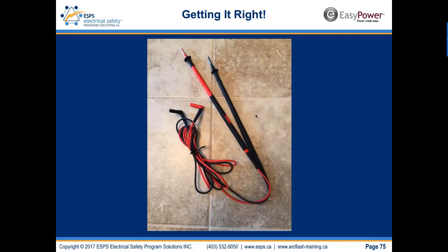There's probe extenders from Fluke that you can actually get the worker's hands further out of the box. That will reduce risk of shock or arcing faults with conductors accidentally being hit by the hands and where they're not terminated properly pulling out of the equipment.